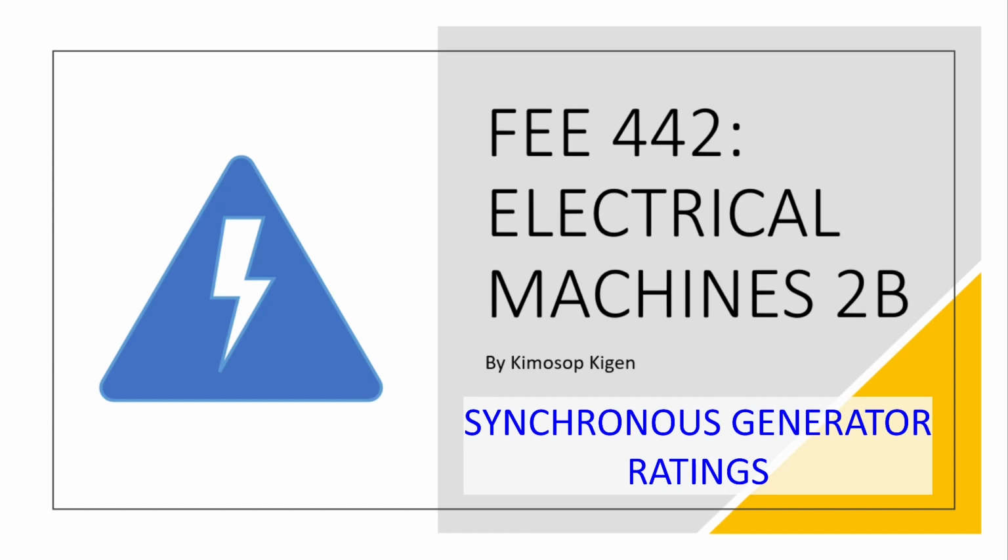So when you have a generator that is rated to a certain number of kVA, we can only output a certain amount of power from that generator. This topic will describe what we call the capability of the generator, and we will then draw the capability curves of the generators themselves. So let's begin.